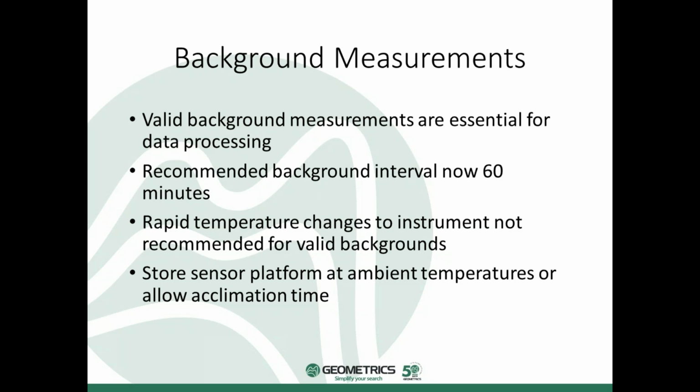So if you're working at a site that is either very warm, say 95 degrees or more, or very cold, below freezing, it's recommended that you either allow for about half an hour of time to let the instrument acclimate to ambient temperature, or you can store the sensor platform, so the cart system, in a temperature that matches the outdoor temperature, so in a non-climate controlled Connex box or something.